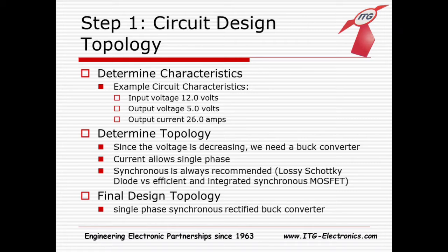Synchronous is always recommended over asynchronous, but asynchronous uses a non-integrated Schottky diode to help manage the conversion. The synchronous form is much more efficient because you have an integrated MOSFET into the converter, so you only have the one circuit, one electronic.